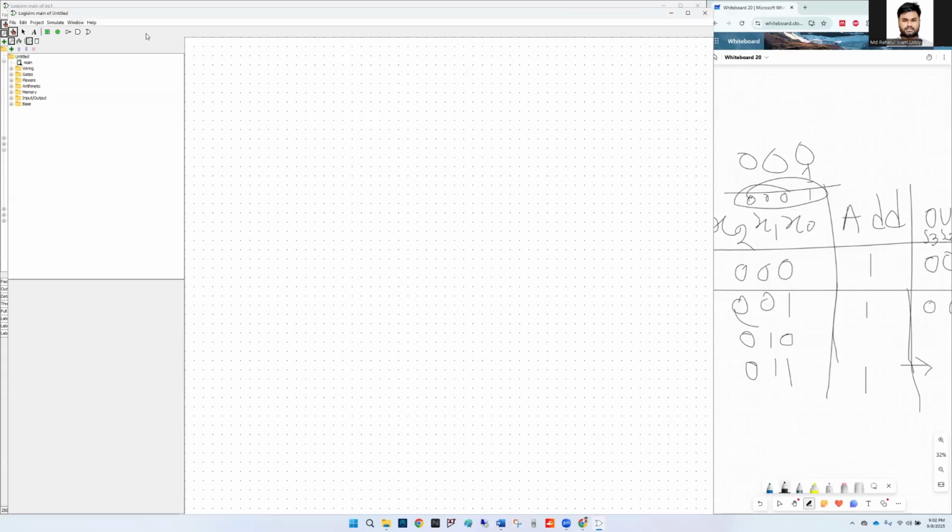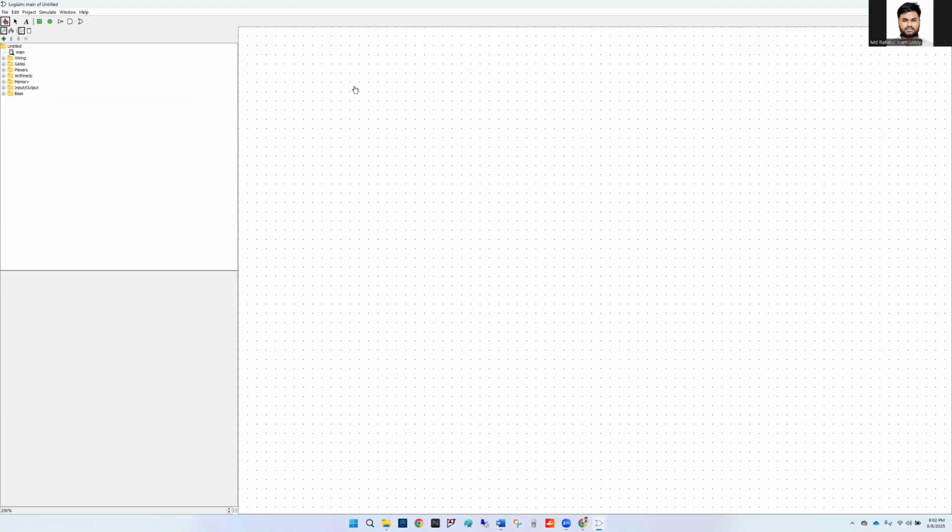So to make your subcircuit, I mean a user-defined subcircuit, we're calling it a user-defined subcircuit. So let's go to the project and now add circuit. You have to put a name, like this: My full adder. I have just named the subcircuit, and the subcircuit we just named should appear right here, under main, I mean after main.